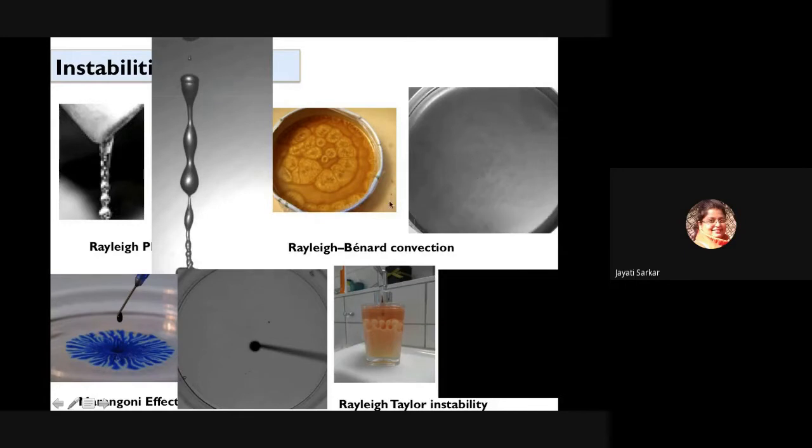Similarly, if we boil some liquid, you can see that there are certain structures appearing because of instabilities on the surface. These are known as Rayleigh-Bénard convection instabilities. This happens when a hot fluid, because of gravity, tries to come up, right? And when you are heating it from the bottom, because the density becomes lighter, and because of the viscous drag effect, this gives rise to different polygonal structures like this, right? So this is an instability because of the viscosity and the gravity effects for that example.